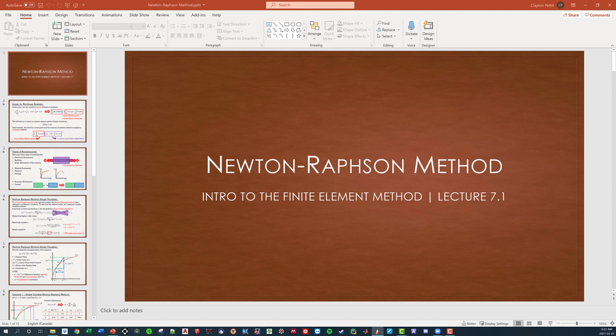Our nodal force vector is basically going to have 3 components. So this is equal to a nodal force vector due to gravity or those body forces. Remember that the body forces was that integral of rho b times N transpose. So that's not too bad. We said that we also had a force vector due to traction, or traction vectors.